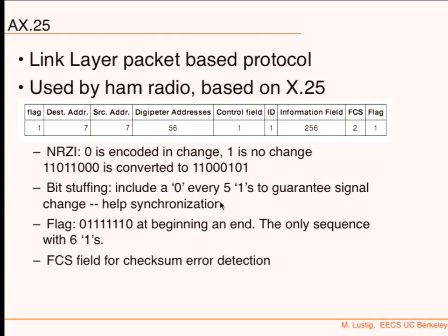And so the longest constant frequency that can happen is only 5 bit lengths. So 5 over 1200, in seconds. That's the longest constant frequency that can happen in this case. Is that enough for clock synchronization? Yeah, because it happens more often than this, but that will be the maximum.